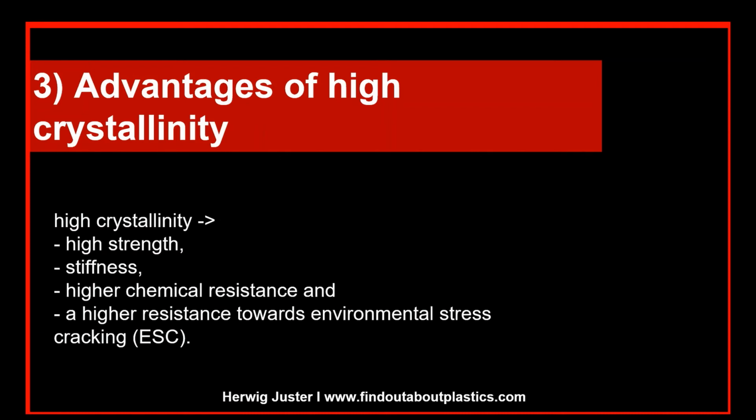Furthermore, the modulus retention of unfilled semi-crystalline polymers above the glass transition is higher compared to amorphous polymers, and this is a result of the crystals. For example, when you take an unreinforced PBT, polyester, it has a modulus at room temperature of 2.3 gigapascal, and at 100 degrees C we still have levels of around 330 megapascal.